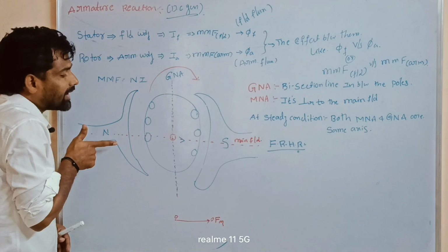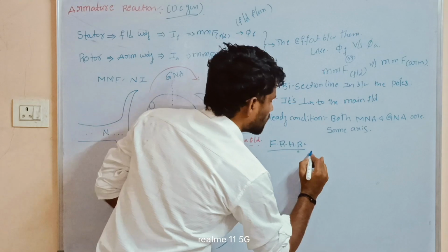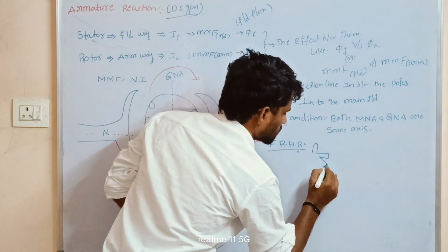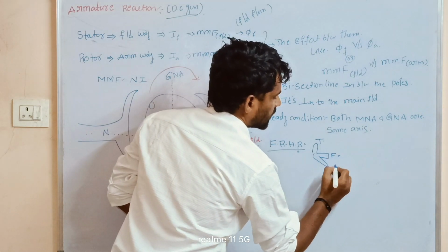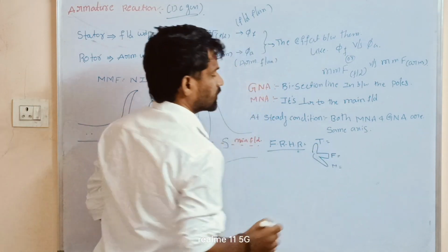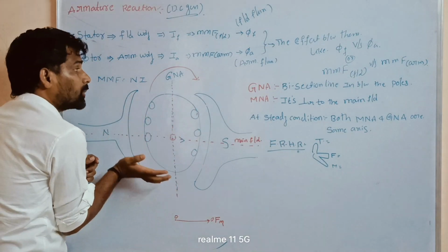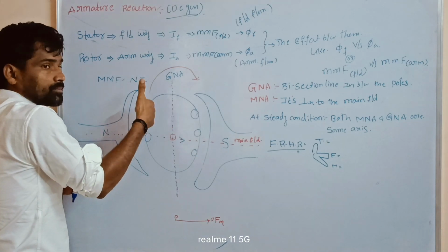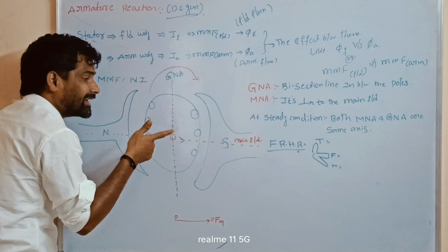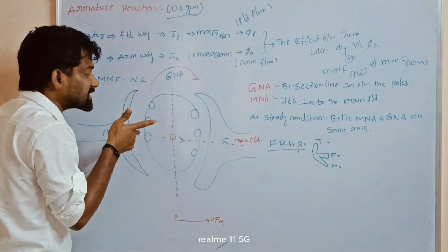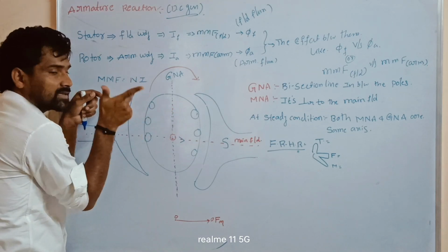So now here the magnetic lines of force are passing in this direction. We consider the thumb, forefinger, and middle finger. The thumb indicates the motion of the conductor. Here the motion of the conductor is from bottom to top, it is rotating in this direction. The field goes in this direction, so automatically the current is entering the conductor from this direction.